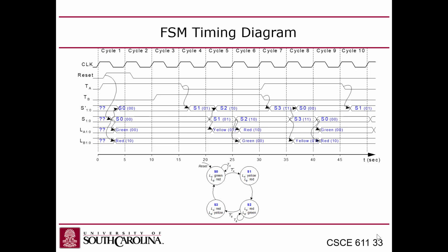Okay, so once we go into, let's see, yellow light is here. Yellow light is only asserted for 1 cycle, and then the next cycle we're in red. And then once we go red on academic, that also triggers a transition to green on bravado. And we're going to stay in that state until there's no traffic on bravado, which doesn't happen until, again, the next cycle, but it happened too late for us to begin the transition in cycle 7, so we wait till cycle 8, and that's when we go into yellow on Bravado. You guys with me?